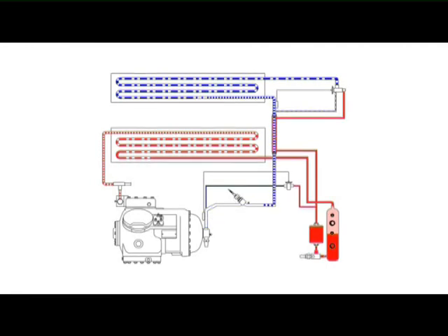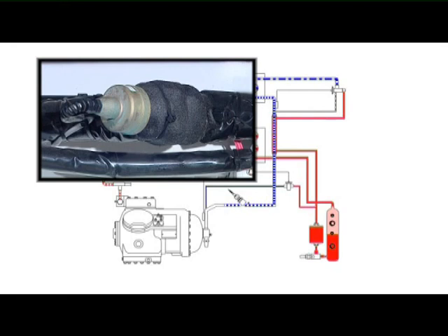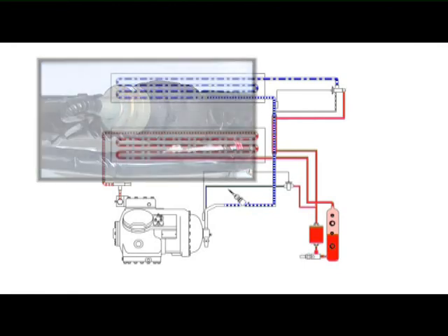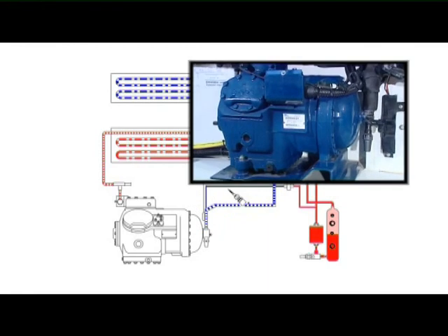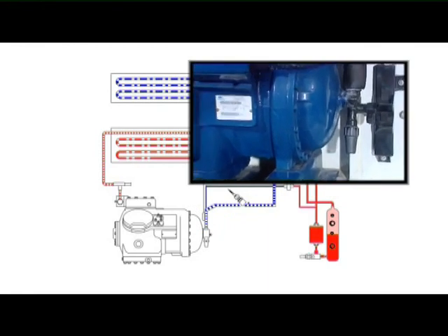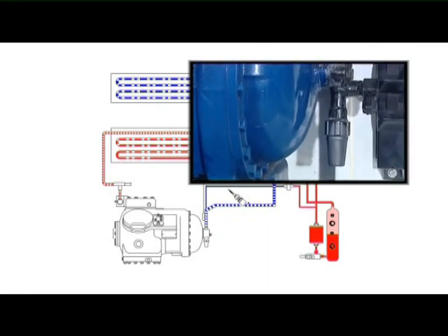On the newer type, the suction modulation valve and the suction solenoid valve are replaced by a single valve, called the stepper suction solenoid modulation valve. The refrigerant vapor completes the cycle and it will return to the compressor suction service valve.